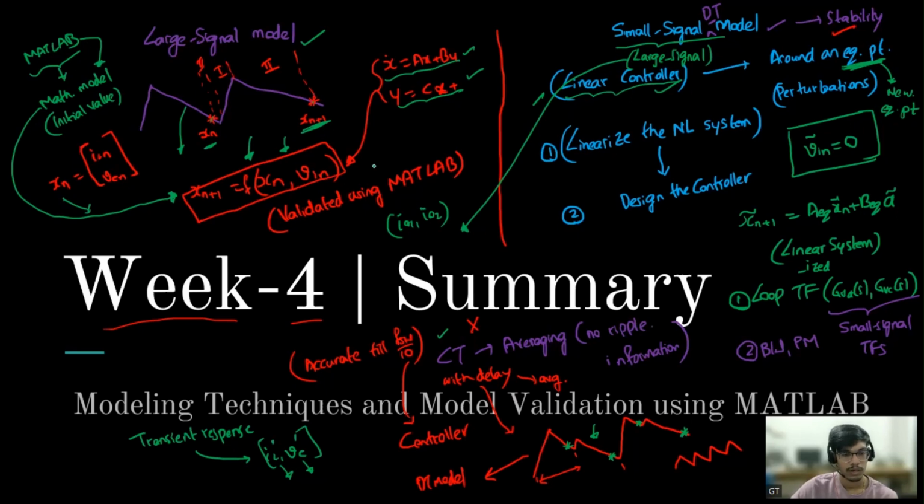But sir, will this work in the transient state also, when the inductor current has not reached the steady state? Yes, it should work. Accordingly, we change our matrices. Say the resistor is V0 by I0, and I give a transient, then the R value will change from R1 to R2. We have to feed this to the code. The code will not know that a load step response is happening. We should tell the code that R has changed from R1 to R2.